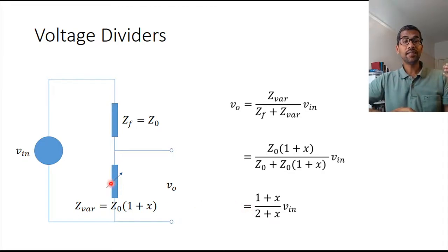So this is a voltage divider circuit. The main thing that you would have to do for using the voltage divider for reactive sensors is have V in as an AC signal. You can't have DC signals when you are using it for reactive sensors.